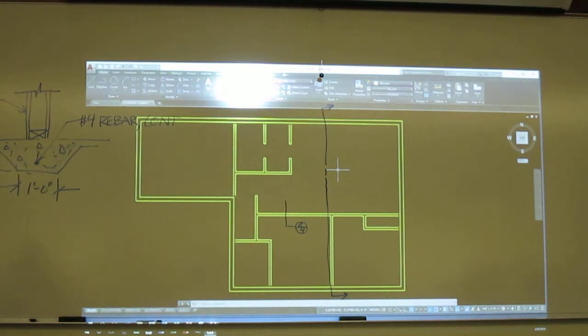As such, and you've got it drawn. Okay, that provides you your, and I'll just put the dimension in here, this is 8. So we've got a 4-inch slab. We come down another 4 inches for this. And we make sure it's 12 wide centered underneath that wall. And there's your detail.